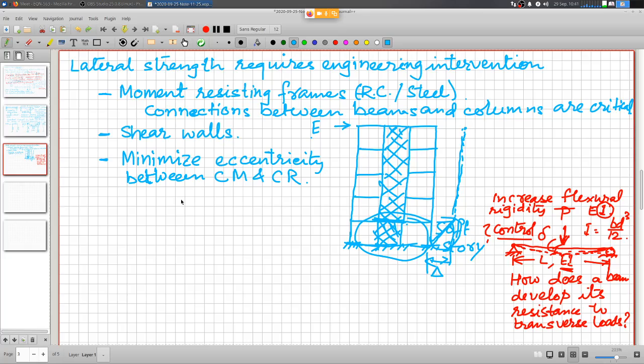And if those have not been designed to accommodate those, sometimes it may not be possible to accommodate these large deformations, because these additional deformations because of the torsion are in addition to whatever deformations the frames will undergo under the influence of this horizontal load or horizontal deformation that is imposed by the earthquake on the system, right? So this combined deformation may be beyond the capacity of the structural elements, and the entire thing will collapse.